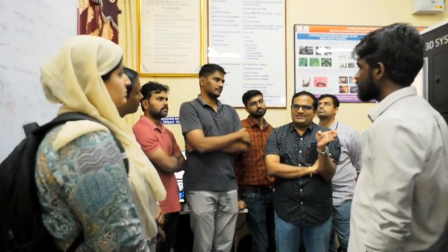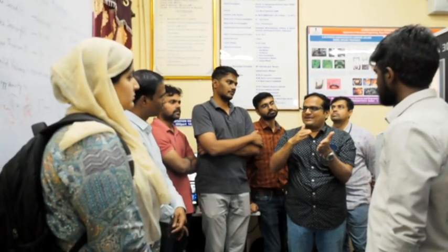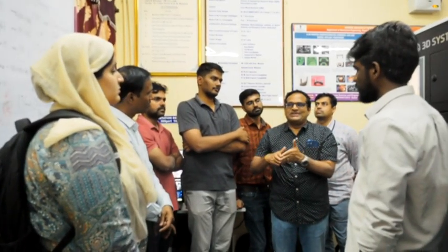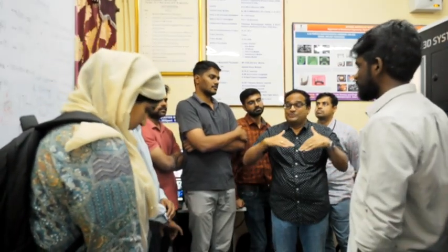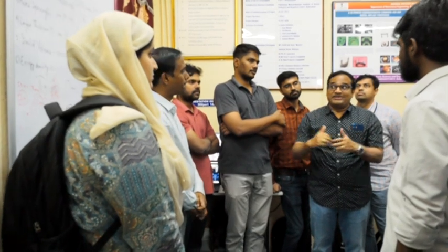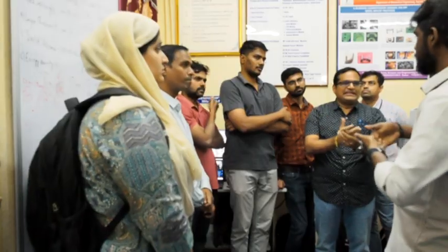Support sometimes acts as a conductor also. If you are not giving a support, what is going to happen? Where will this heat be dissipated? It won't dissipate heat. So the support acts as a conducting medium sometimes. Otherwise, if you are not giving supports, you have a huge heat problem, kind of delamination. Delamination will come, distortion mostly.